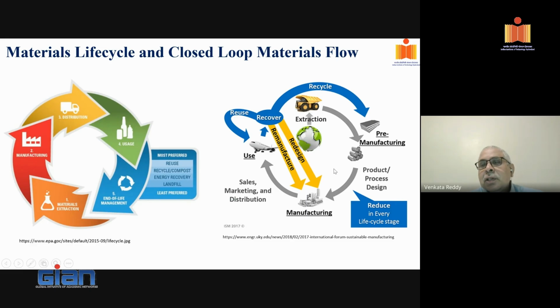Okay, now you shall reduce the material usage in the design. Then today you have a lot of tools, a lot of design things, and the corresponding manufacturing processes to implement them. Sometime back, if you wanted to make a component, let's say having the fatigue properties, you might have chosen a forging process. Okay. Forging process has its own constraints, but today the combination of forging and additive manufacturing together gives you a lot of freedom, and then you can use topology optimization and design the component with lesser material and with the required properties. Okay, so hybridization of processes is also possible in this. I'll show some of them at a later stage.